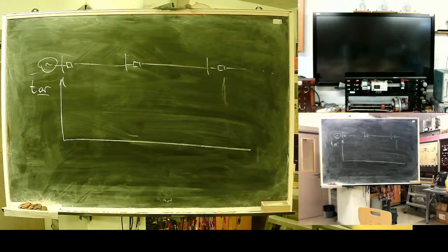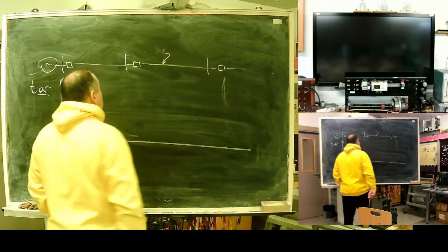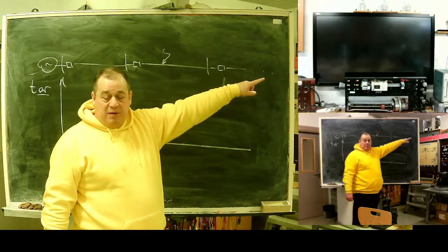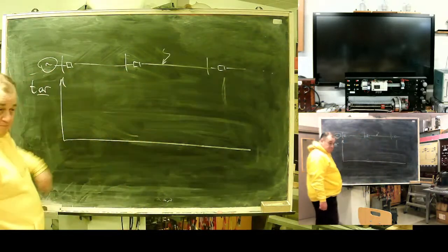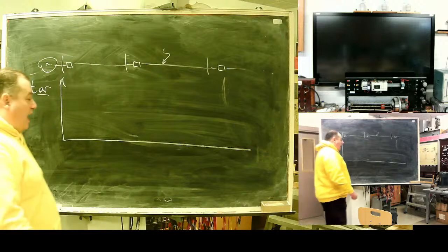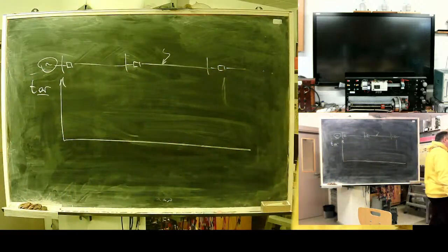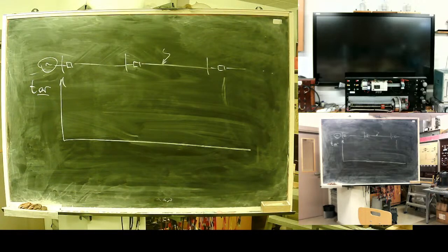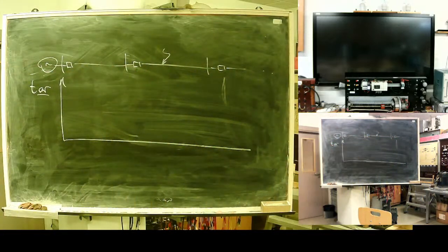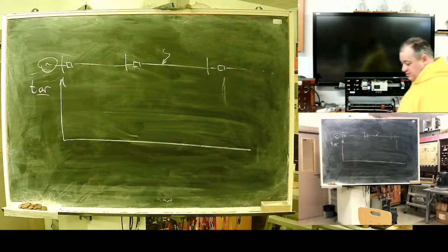So in this case, what will happen? For example, we had a fault here, this switch disconnects, but everything going forward will also be disconnected by minimal voltage protection. We need to restart the network, and it's done by auto reclosing. I don't like such designs where everything should be corrected by auto reclosing. We can omit selectivity because auto reclosing will cover everything. I don't like this approach, but it exists in reality. Allowing non-selective operation, auto reclosing will do our work.